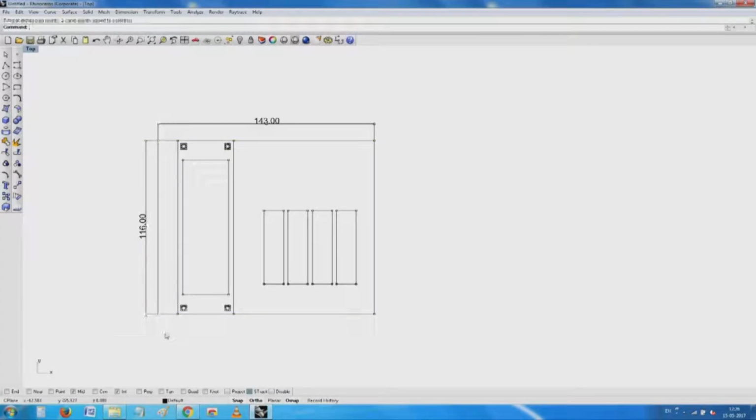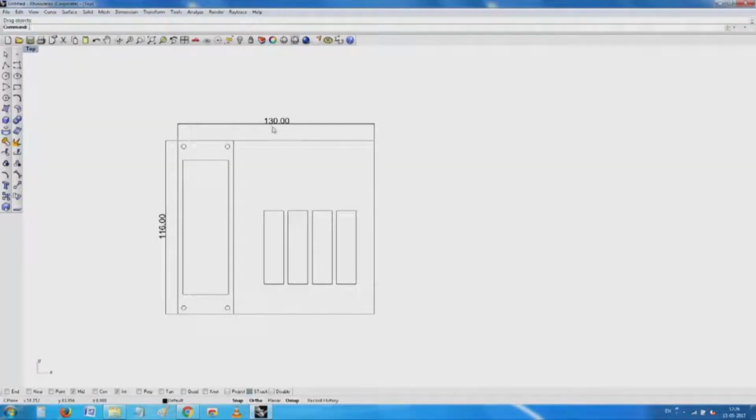See here, slowly I am trying to make them as compact as possible. What started as something, now you see here my constraint is 116 mm is the width of the device. So I still have almost, if I leave around say 10 mm all around, I end up with a printed circuit board typically about 100 by 120 mm.